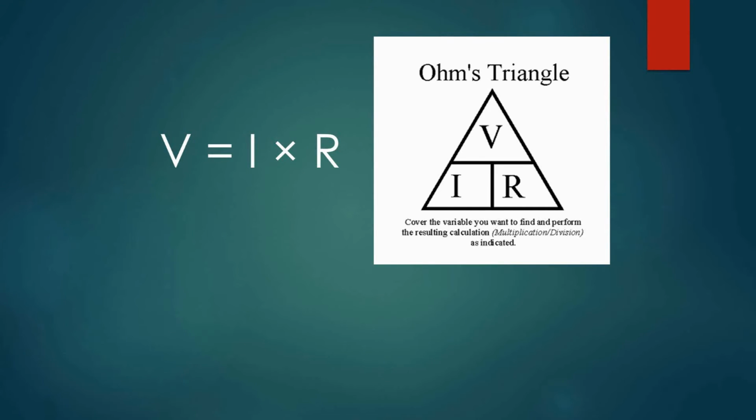We also have a very helpful tool called Ohm's triangle to work with. If we cover up the variable we want to solve for, we can tell which formula we must complete. If the variables are across from each other, you must multiply. If the variables are above or below each other, you must divide the top variable by the bottom. For example, if we cover up V, we see that we have to multiply I and R together. If we cover R, we must divide V by I.